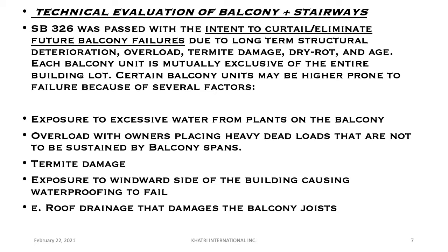So you could theoretically take a 100-unit project, a 100 balcony project, and you could inspect, say, 20 of those or 15 of those, and you could selectively choose. I'm not saying that people would do this, but you could choose the balconies that are not overloaded and don't have potted plants and make a conclusion that they're all good. And that's where you get into a dangerous situation, because if you ignore the balconies that have these problems, then you're ignoring the problem. And termite damage.